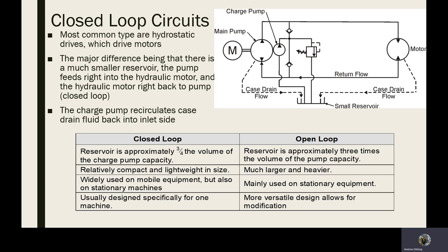These check valves, as you see, are a V with a ball in it. Generally, they have a spring inside of them, and the spring is a preset pressure. So if the pressure of the fluid is greater than the spring pressure pushing down on the ball, the pressure of the fluid wins. As this pump comes up to speed and pressure, it charges the system, driving out any of the air that may have leaked in.